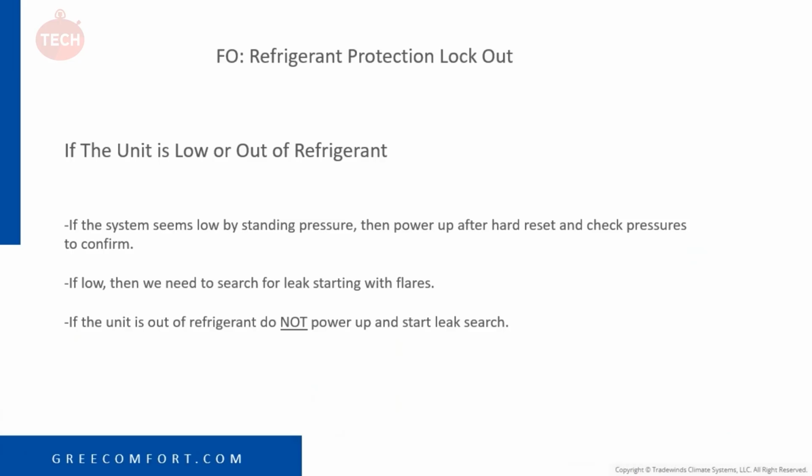And it also depends on set point. If that unit is set for 4 degrees or more than the indoor temperature, the unit is going to ramp up higher to achieve set point. So it all depends on set point, load conditions, and indoor and outdoor temperatures for your running pressure.